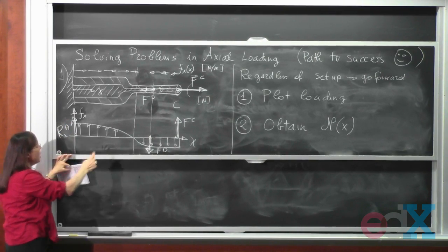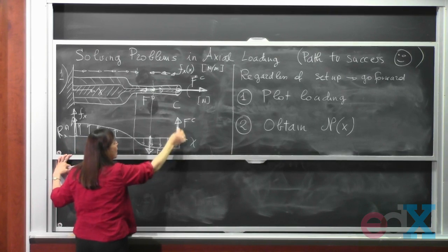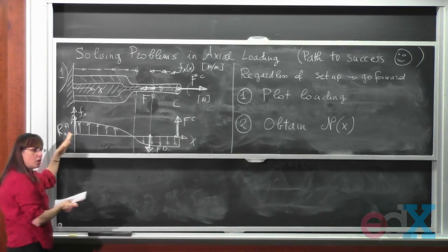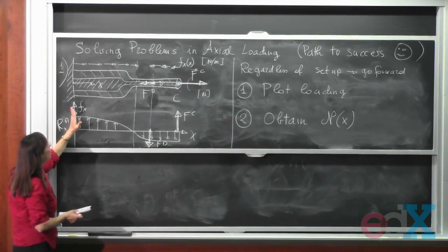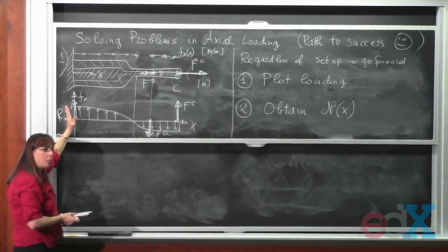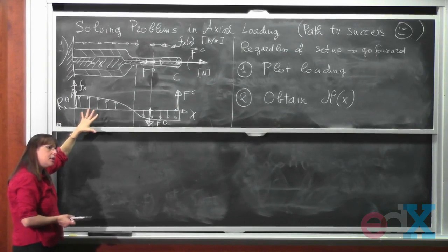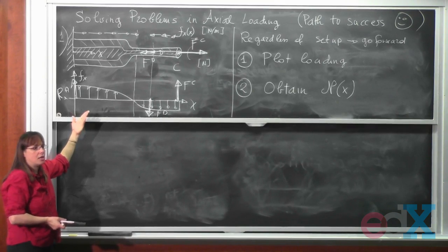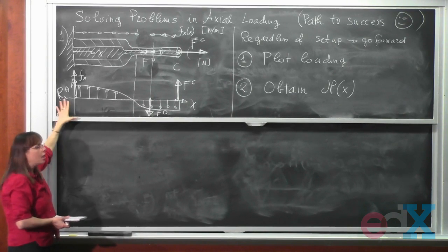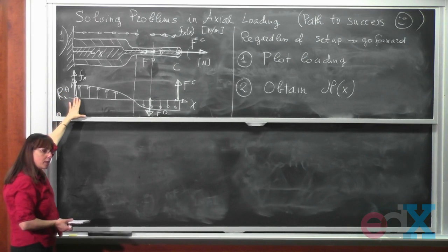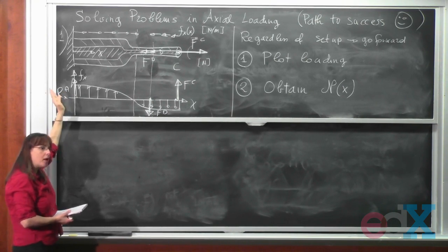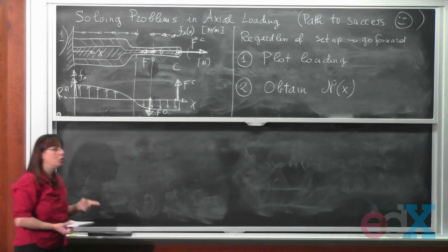If you plot it this way, what that means is that you expect this plot for everything to work out to go eventually to 0 here. But essentially here is the reaction force at the support. Normally I don't plot it in these problems because I'm really focusing on what the loading is. RXA is an unknown, I do not know yet. But if you want to plot it in, that's the way it would go. It's a concentrated loading positive in x. That's a good question.